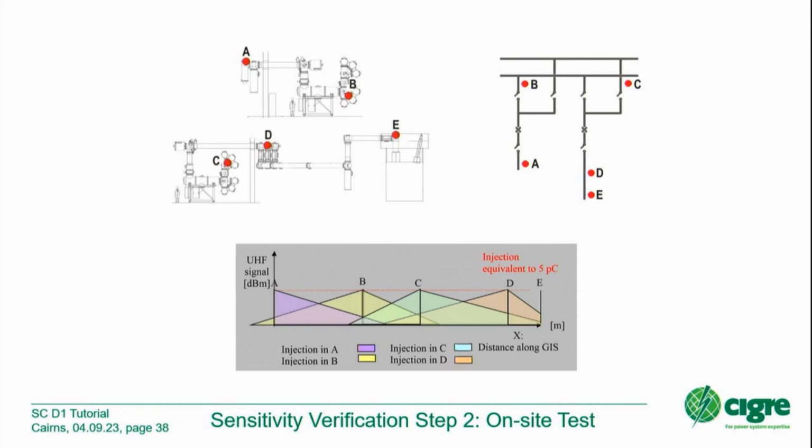I have a question along a similar vein, in that we recently had a failure of some equipment. We'd recently connected a PD monitoring system to it and done a survey of the site, it being a relatively new build, and we found no traces of PD. We then had a failure caused, we believe, by a void in an insulator, actually part of an insulated drive rod for a circuit breaker.